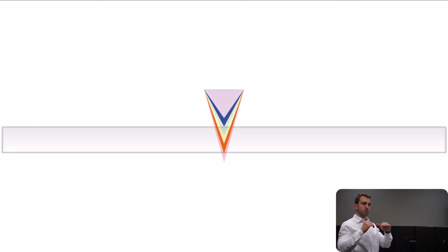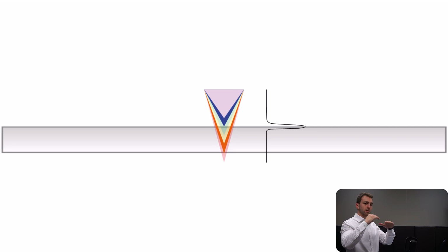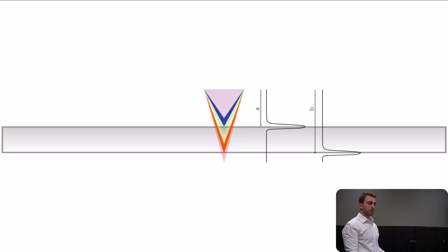Now you might think, what does the distance have to do with the thickness of glass? That's actually pretty simple, because we will get a reflection at the top side of the glass and one at the bottom side of the glass. And since these reflections are both converted into a distance signal, we can then calculate the thickness of the glass by subtracting the two measurements from one another.